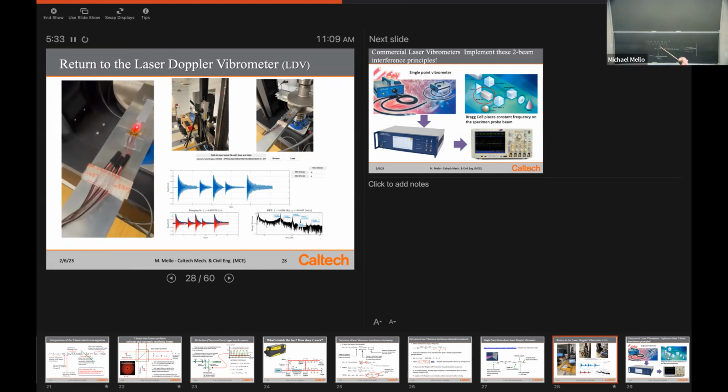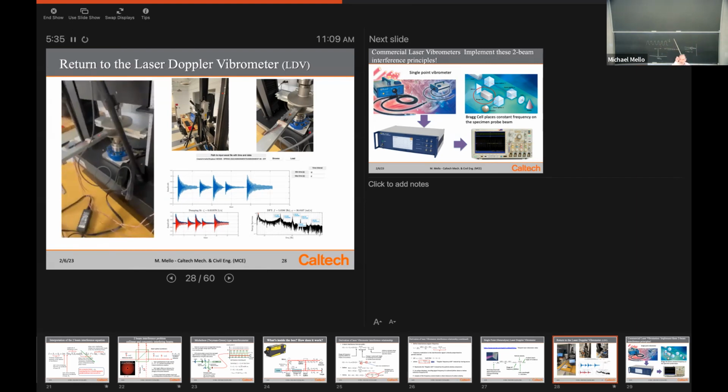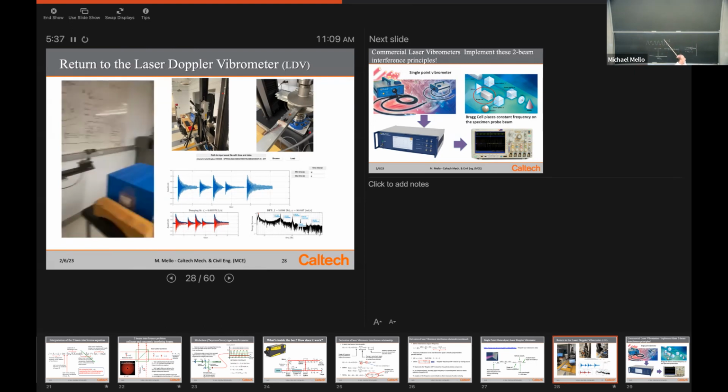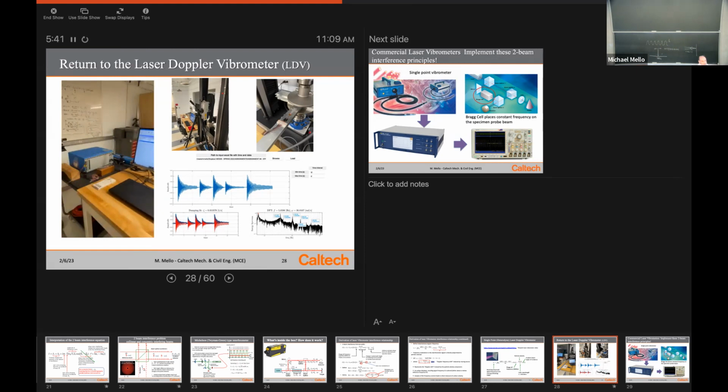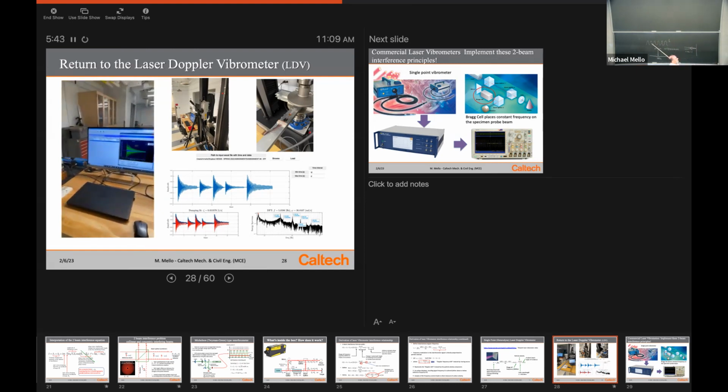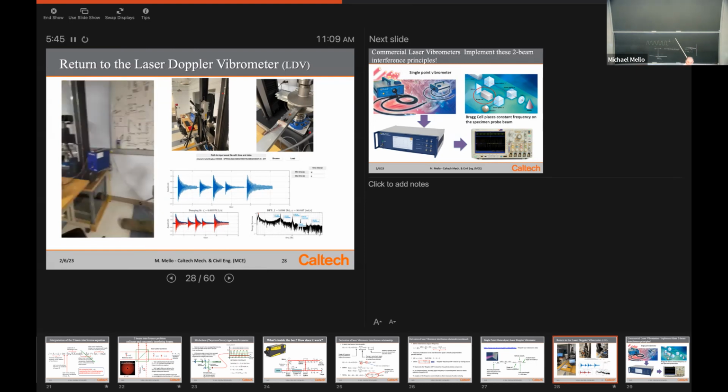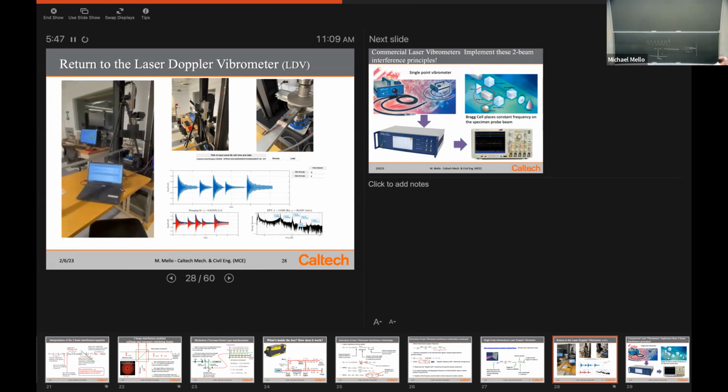All right. That's just the iPhone freaking out, trying to focus on that light beam. So sometimes it defocuses, sometimes it doesn't. Again, the signal that we get out is automatically registered. And then what you do with this in the vibration world is you take Fourier transforms of this data, and you try to identify these sharp peaks in your data. And those sharp peaks are resonant frequencies of your structure, okay?